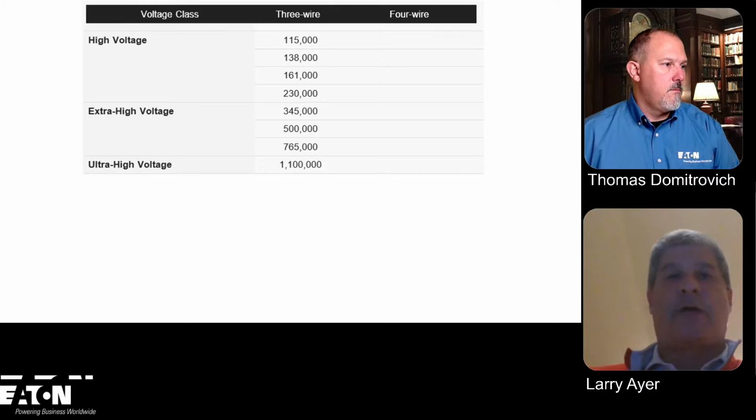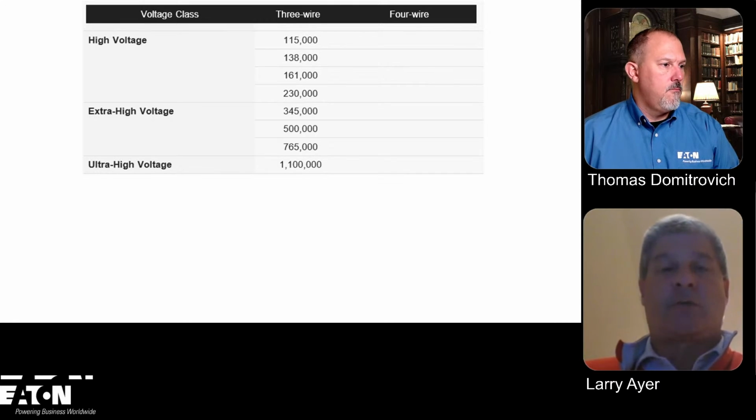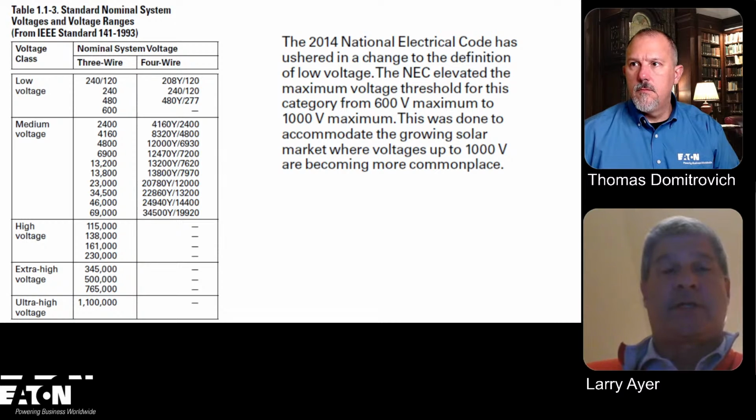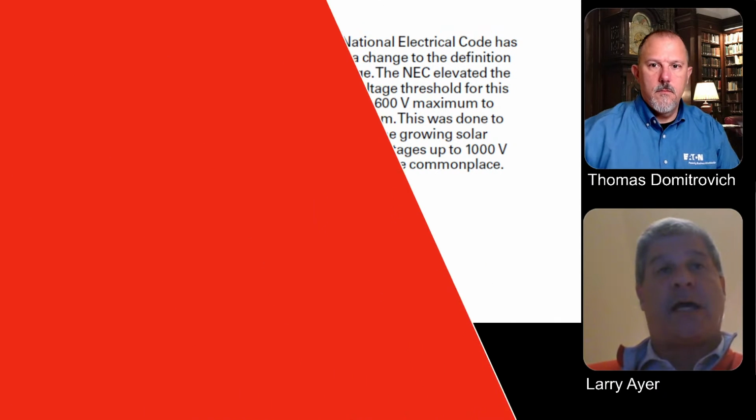Right, but think about it, if you have a 100 amp breaker, you take those wires, you terminate them on a breaker, and when you do that, those wires are very close to each other, and there's significant heat buildup. So part of the reason why you have to derate those breakers and not load them up to their full ampacity is because of the close terminations and where they're located. If you take something like a 5 kV switch, there is a significant amount of space in those, and the way that the equipment's constructed allows you to rate it for 90 degrees to 105 and higher, and that's why it's 100%.